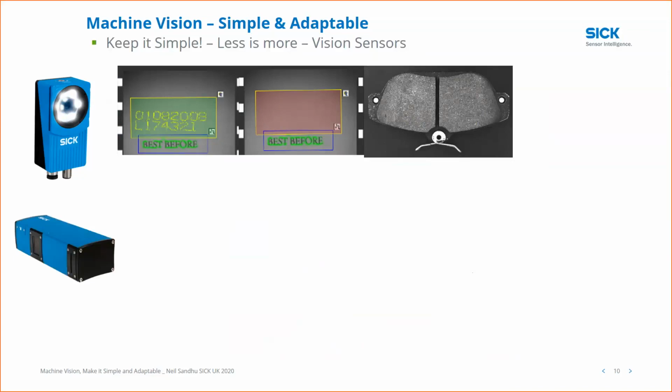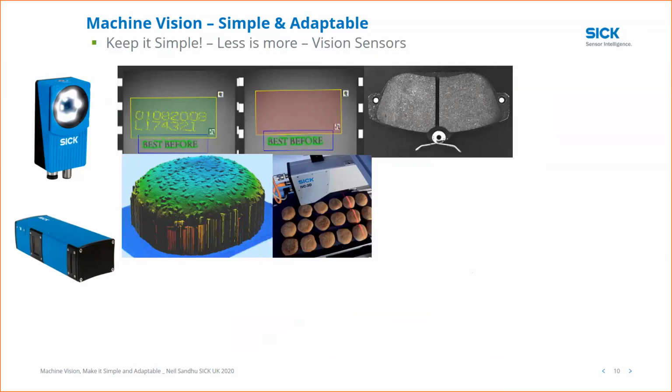But then we can now look at vision sensors in a different way. We have 3D vision sensors. Those sensors now are not using the contrast-based imaging system, but they're using a height-based imaging system. So they're profiling objects in 3 dimensions. So not only are you getting the X and Y measurements possible, but you're also getting the Z, the height measurement. What does that give us? So here's an example of a food-based product. That means that if we have height information, we can look at things like volume. We can look at total size and measuring the diameters in the X and Y, but also in that Z axis. Even in this example, counting, if need be, the number of seeds on that particular object.